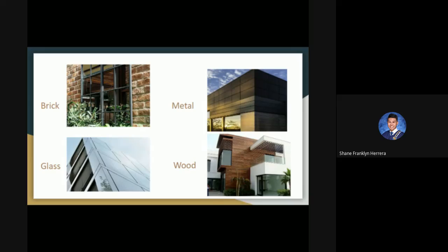In time, when your wood is exposed to outdoor conditions, there is a tendency that it would fade and wouldn't look like it was new, because weathering will happen. So it is good to maintain it with your pigmented stain or paint. The long-term performance also hinges on periodic maintenance and recoating when required. This type of cladding can be fixed on steel frameworks.